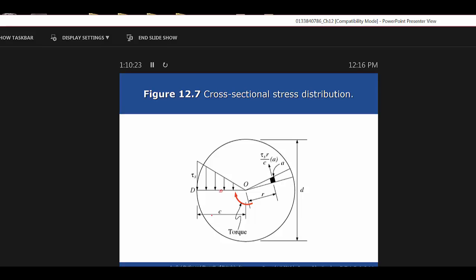If you were given that on a test, you would still have to do that, and that would be one I would probably not look the other way on. Okay, so for that shaft, the next increment up would be a 110 millimeter shaft, and you would want to go up, but you wouldn't want to go down if it was 105. Because you'd screw up your shear, wouldn't you? You wouldn't be meeting that value.